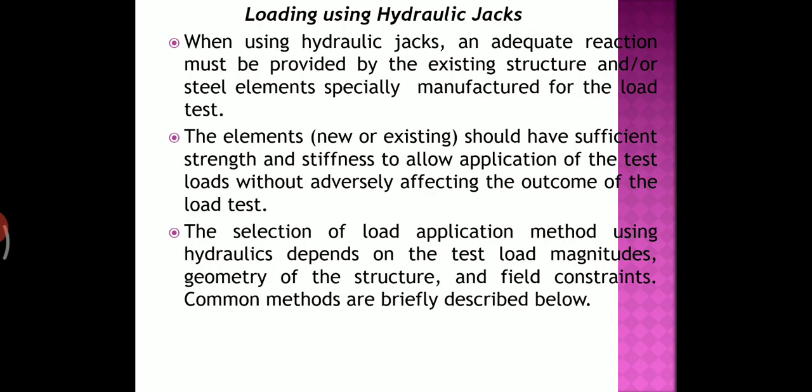Then the other one is loading using hydraulic jacks. When using hydraulic jacks, an adequate reaction must be provided by the existing structure and/or steel elements typically manufactured for the load test.